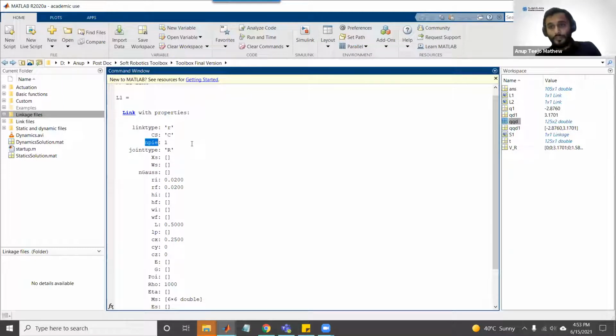For a soft link, the number of pieces will be the joint plus the number of divisions of the soft link. Later I will show an example of a soft link with 2 divisions. In that case, the number of pieces will be 1 for the joint and 1 for each division. So it will be 3 pieces for a 2 division soft link.